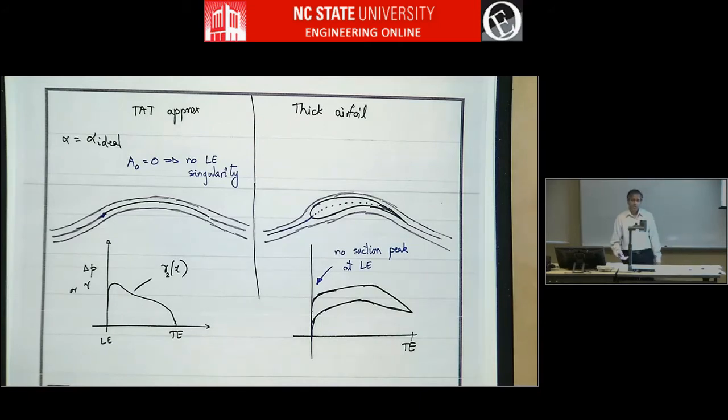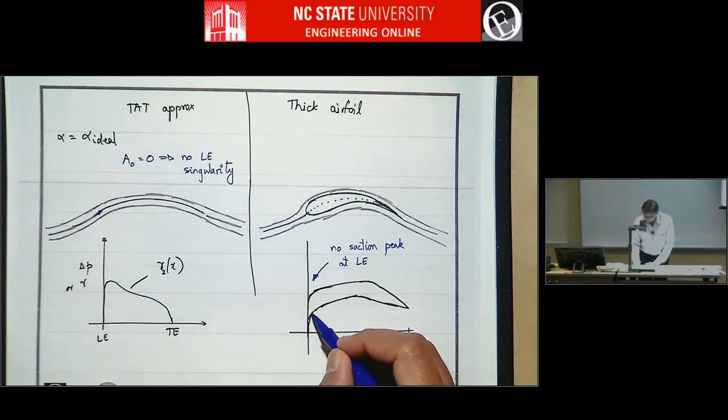And so if you're designing a laminar flow airfoil, remember, at moderate Reynolds numbers like 1 million to 9 million or something, if you have a suction peak, that causes an adverse pressure gradient behind it, and so you lose laminar flow. And so this is a condition at which, provided the airfoil is designed with favorable gradient, you will have lots of laminar flow.